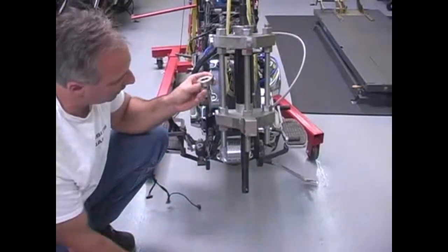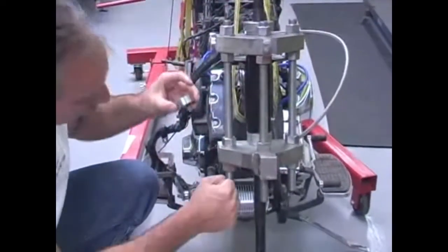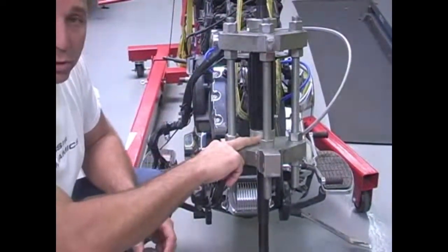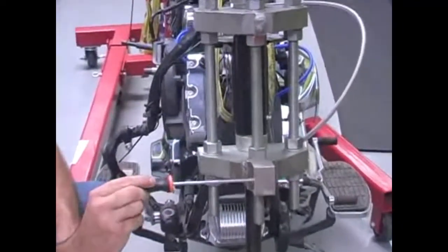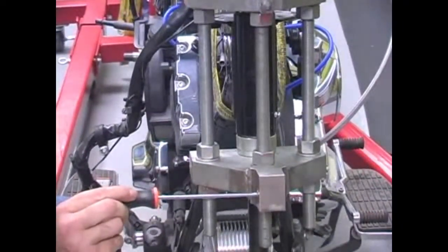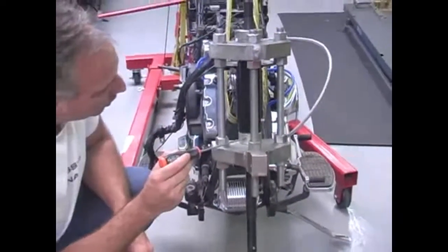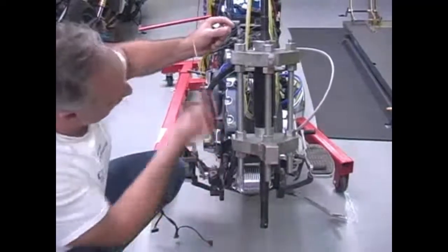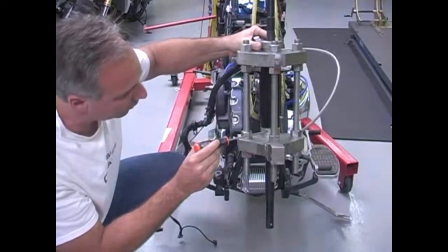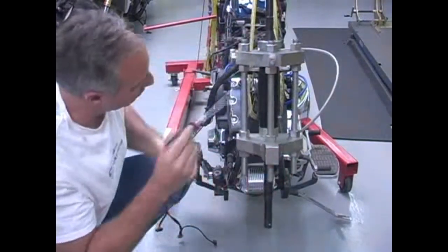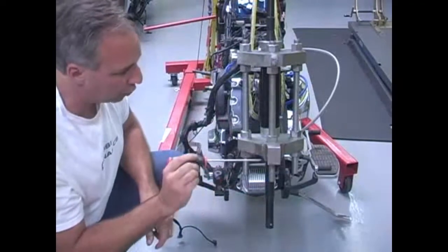And so what that's allowed me to do is put one of these at the top, one of these at the bottom, stick the shaft through, put my spacer down here at the bottom, which gives me a mechanical advantage as far as stretching out the neck goes, and it decreases the pressure needed to do that. And what I'm able to do now is put this shaft concentric to the steering head, put my little cheater on there that increases my leverage, and then I'm able to build up the bracing that allows me to pull.